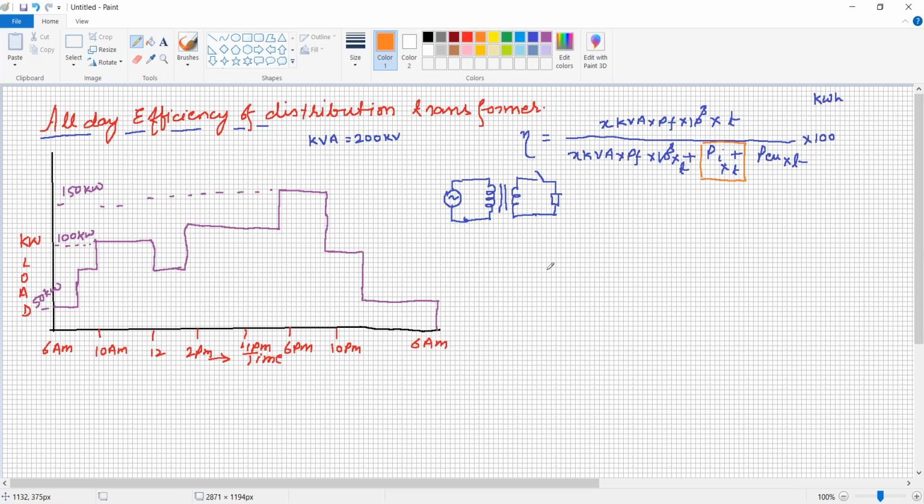So under such a condition, whenever the transformer is designed, it is designed at low flux density. If the transformer is designed for a low flux density, definitely the core cross-sectional area is more, isn't it? And when the core cross-section is more, definitely the transformer cost is going to increase. But to minimize the cost, someone is going to design the transformer at a higher flux density.